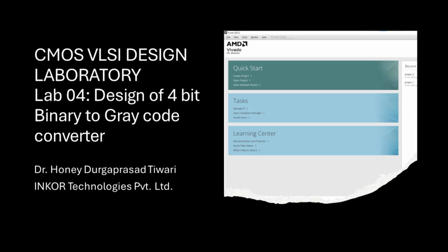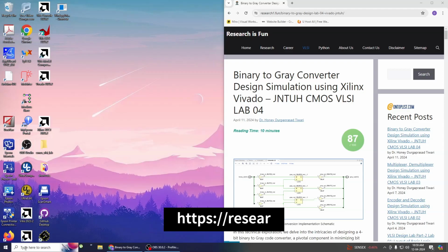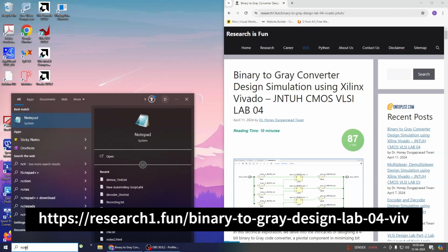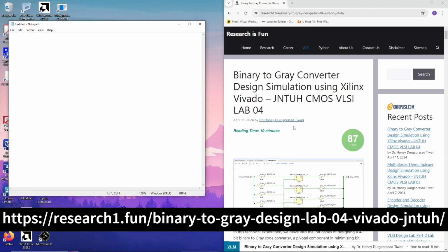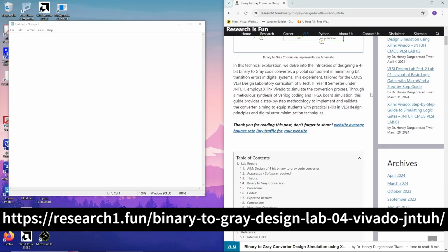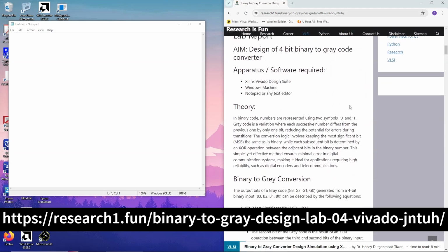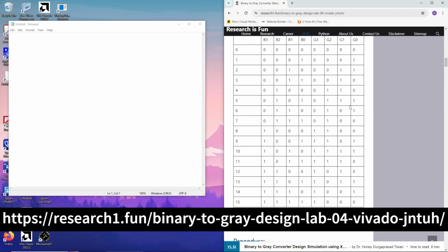So let's get started. To simplify the Xilinx Vivado project creating process, we shall create our source Verilog files and Testbench beforehand. In a Windows machine, open Notepad. Write the Verilog logic in the file.